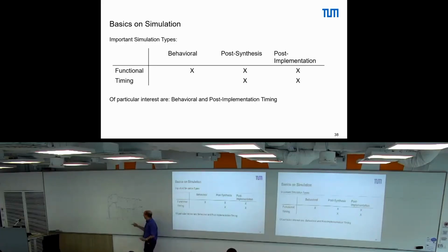The original task was to find out if we can meet this clock frequency. So what do we have to compare? T_D max should be larger, smaller, equal, smaller? Which clock, maximum or minimum? Minimum. Is this all? Let's look at the cheat sheet.